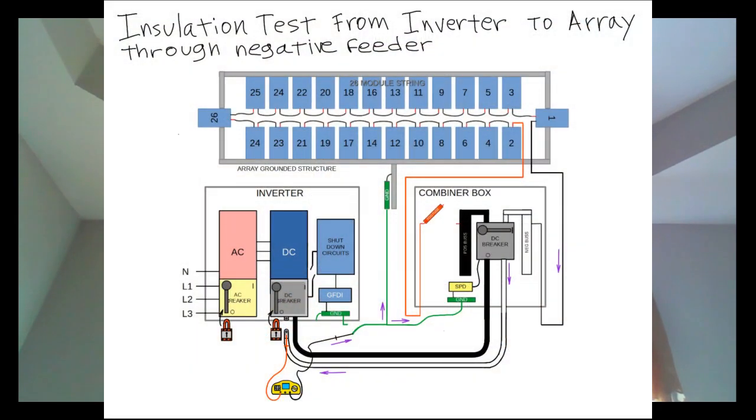Continue this procedure on each PV string circuit and identify each outlier, which may indicate a ground fault. If you're using a multifunction tester like the SMFT 1000, follow the procedure prompted by the meter.